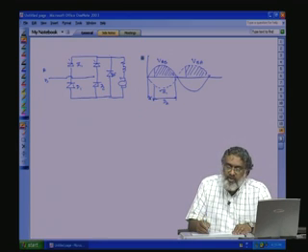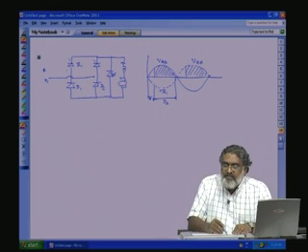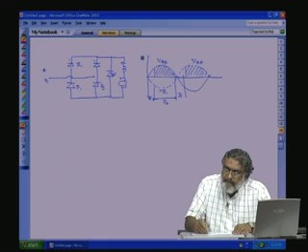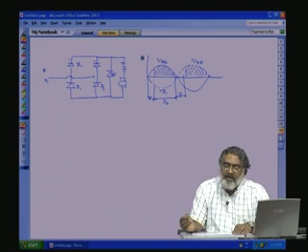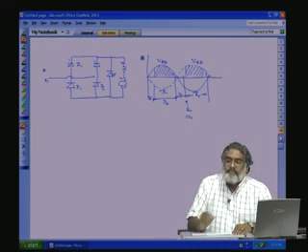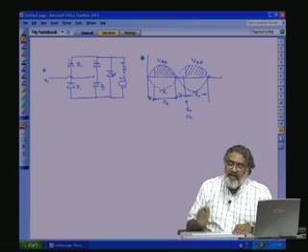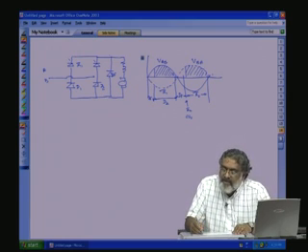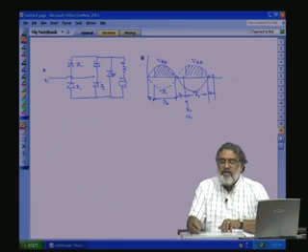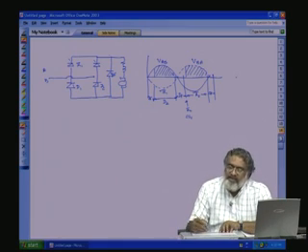Now, the moment the voltage goes negative, what will happen? This voltage going negative means, because of the inductive load, that slight negative will forward bias DF and during this portion again DF will conduct. Okay, DF will conduct. Again when thyristor TH2 is turned on here, TH2 will conduct till this period. Here again the freewheeling will work out till TH1 is turned on. So, this is a full wave rectification, if you see here, with the firing angle control.